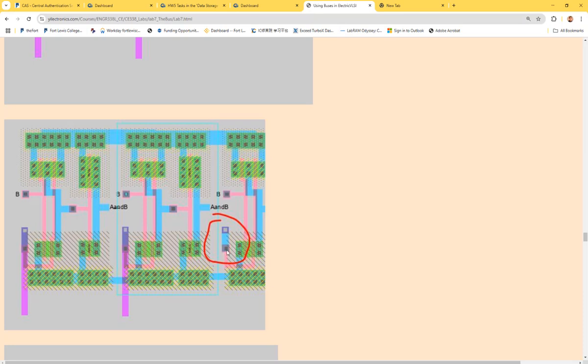I did a metal 1 connection to the poly to metal 1, which makes sense because metal 1 to metal 2 is here, and poly to metal 1 via is here. So that's why they are interconnected, from poly to metal 1 and metal 1 to metal 2. So they are connected. That's why I can directly use metal 1 to short these 2 vias. These 2, okay? These 2, which is over here.